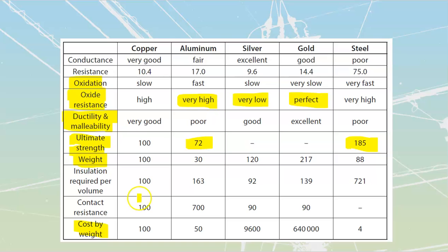Contact resistance, that's going to be this one down here, is the resistance per area of contact between two conductors at fixed values of pressure. These are engineered values over here, but it's going to depend upon the type of material. Copper over here has only got a contact resistance of 100. When we press copper up against copper, it relatively easily flows. Aluminum, not as much so, which means that we have to be careful with the aluminum conductors that we are going to use inside of here.